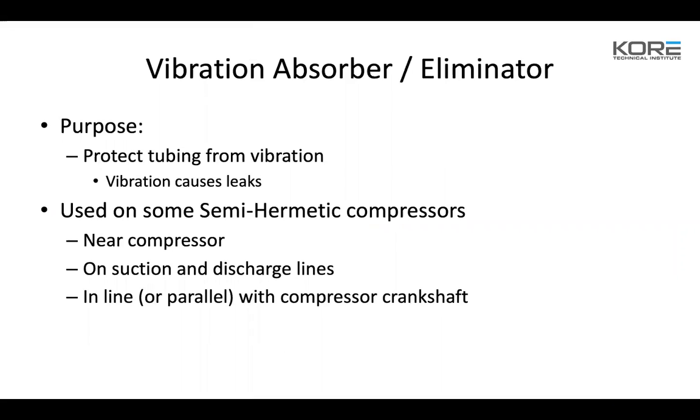Vibration absorbers or vibration eliminators protect tubing from vibration and leaks, used on semi-hermetic compressors, near compressors, on suction and discharge lines, and in line or parallel with compressor crankshaft.